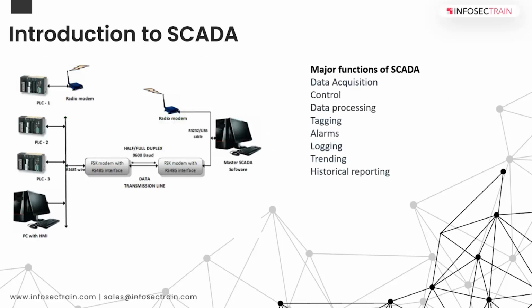Right. So we saw PLC, we saw DCS, and this is SCADA. SCADA in itself stands for Supervisory Control and Data Acquisition, as the name indicates. So SCADA is not hardware in itself. It is basically an application which supervises and acquires the data received from different locations.